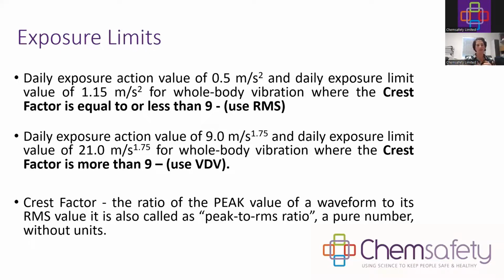whereas waves with smaller peaks will have a lower crest factor. So when your crest factor is less than 9, you'll use the action value of 0.5 meters per second squared for your daily exposure, or you'll use the exposure limit of 1.15 meters per second squared. And that's usually your RMS. You'll use your RMS for that, and it's your root mean square.